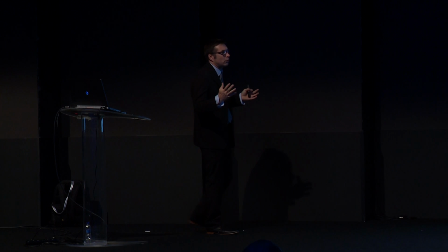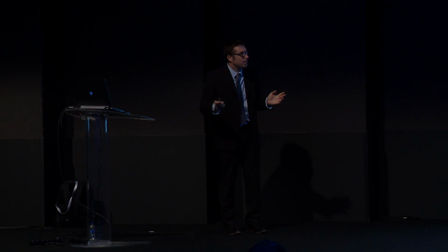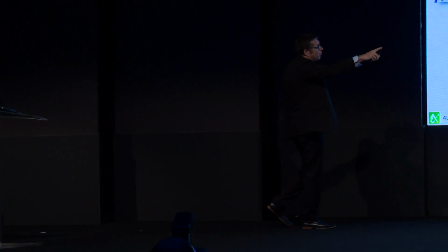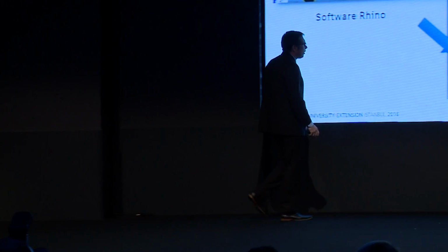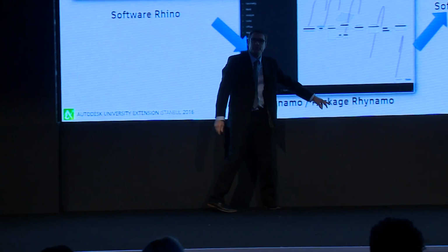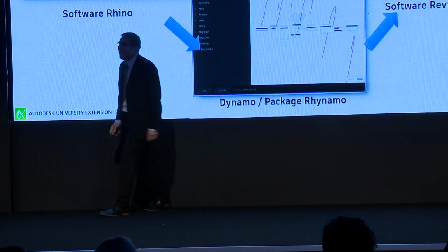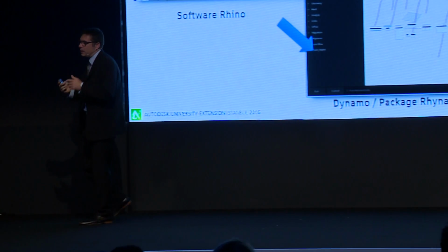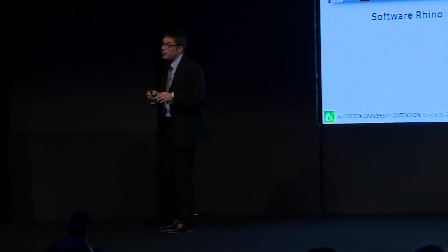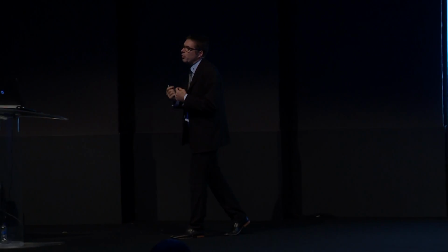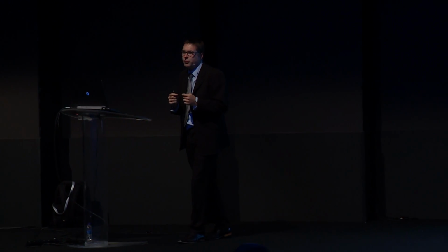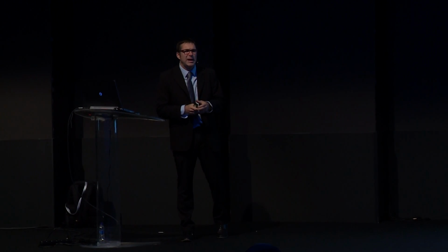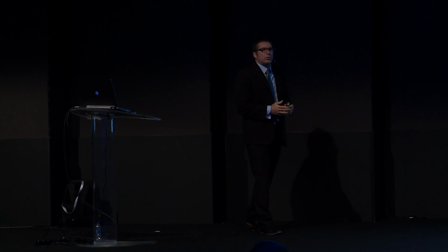And of course, if you want to enlarge the connection between other software, for instance, you can connect Rhino to Revit using a special package called Dynamo in native way, because currently, when you try to import a Rhino file into Revit, you need to import the SAT file. And SAT file in Revit is not very useful.